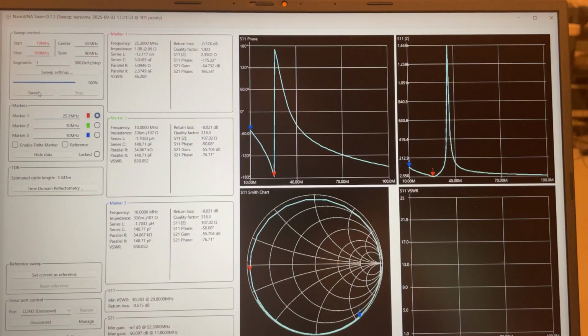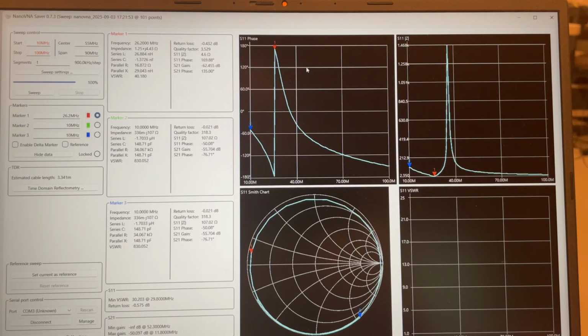We said that the quarter wave frequency, where the capacitive reactance and inductive reactance are equal, at the 0 degree phase angle, is 25.7 megahertz. Again, we look at the lower side, 25.3 megahertz, and the upper side, 26.2. If we average those together, it equals the 0 phase angle frequency, 25.7, as I showed on the other slide.